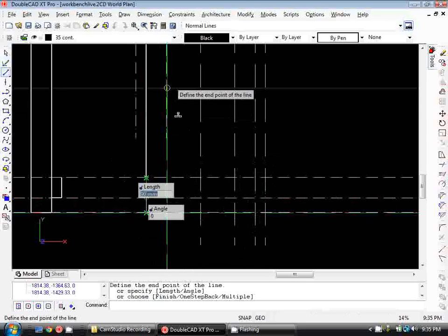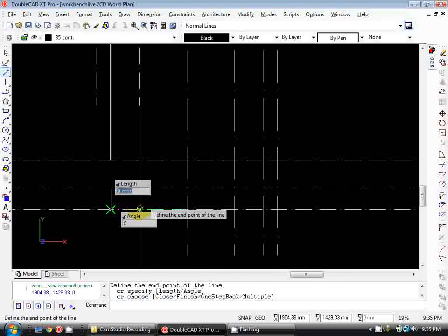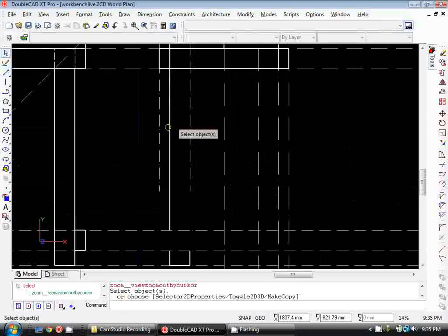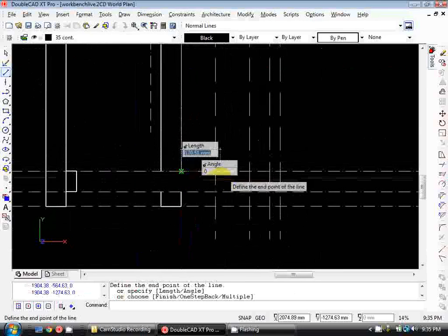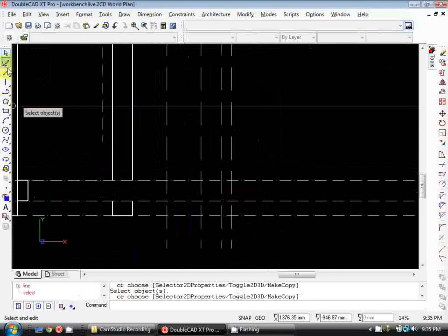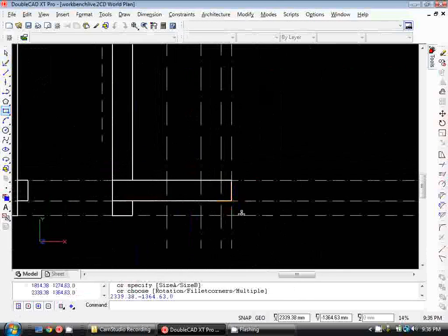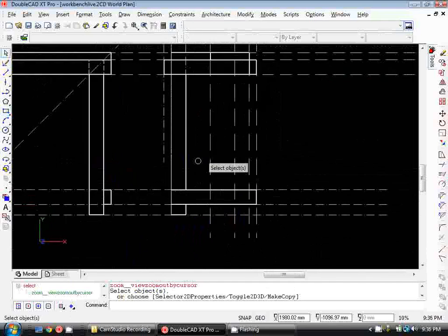This is the other edge of my leg. So if I click here and here, that's a 90 wide piece of leg. Hit space again to draw a new line, snap that down there. Now I'm going to hit the rectangle tool, snap from that point to that point. So this is the elevation view of this little framing timber.